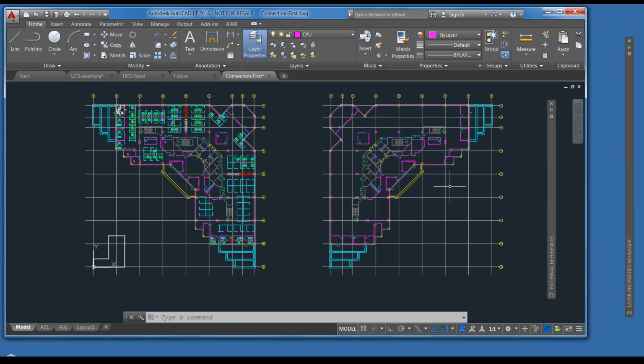Of course, you still have the option to use eTransmit. So say you have a drawing that has lots of external references and image files. The command eTransmit just grabs everything up and puts it into one compressed folder for you to ship out.